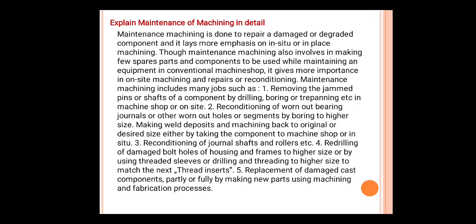Reconditioning of journal shafts and rollers, etc. Re-drilling of damaged bolt holes of housings and frames to higher size, or by using threaded sleeves or drilling and threading to higher size to match the next thread inserts.